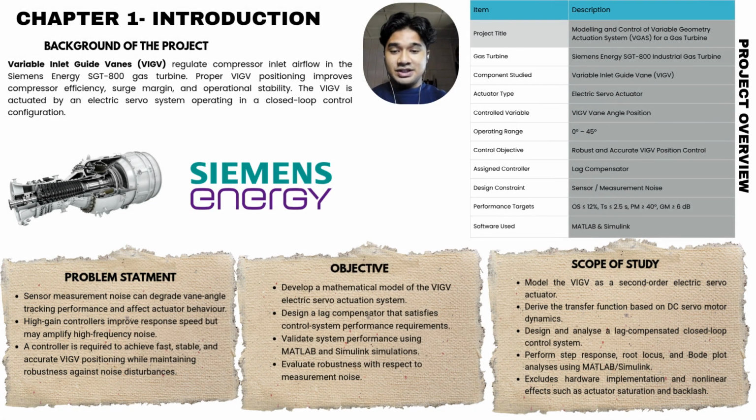Now let's see our introduction. Our project focuses on the modeling and control of the variable inlet guide vane, or VIGV, in the Siemens Energy SGT-800 gas turbine. The VIGV regulates the airflow entering the compressor and plays an important role in maintaining compressor efficiency, surge margin, and overall turbine stability.